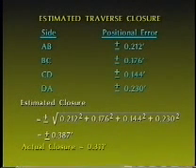You can also use this estimated error to determine the equipment and procedures necessary to have a survey conform to a classification of accuracy. In your workbook, you'll find the classifications of accuracy from the Caltrans Survey Manual.